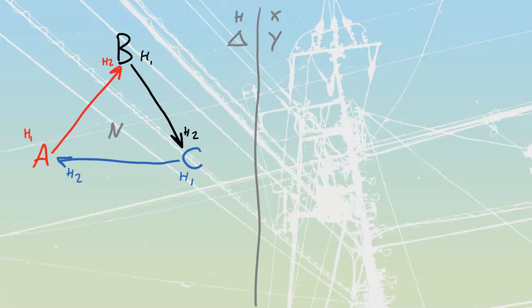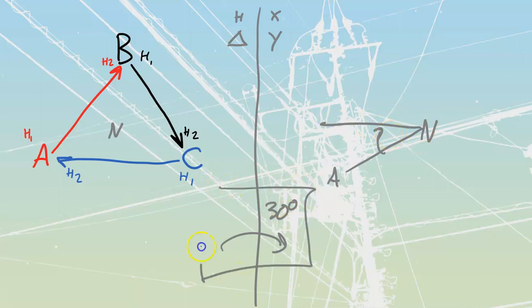What's going to happen is we are going to have to now transfer to the low side, and once again, as we said with the previous connection, anytime that we have a transfer from Y to delta or delta to Y, there is always going to be a 30-degree displacement in where the A to neutral was. In other words, originally we had A to neutral like that, and now we have to rotate that up so that my A to neutral is going to look like that. So since we know that we have this, it is a law, it is a rule, you can't fight it, don't fight it, just accept it.